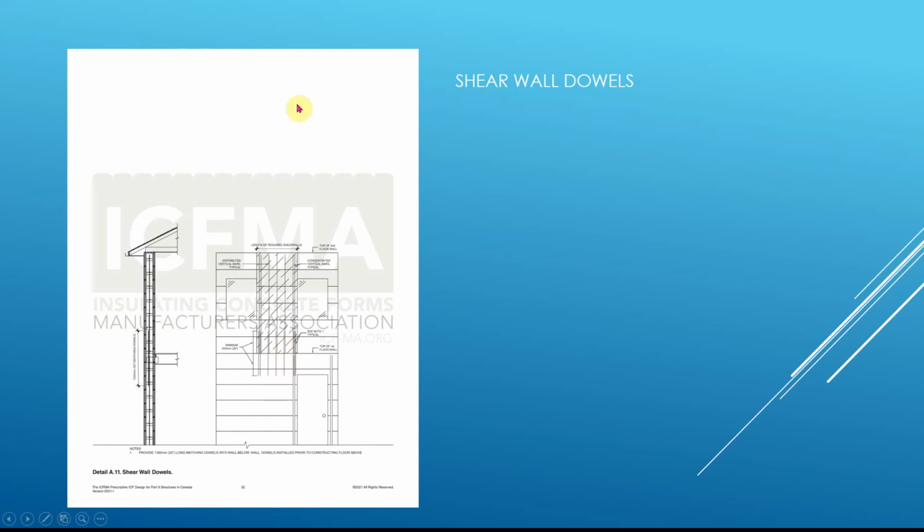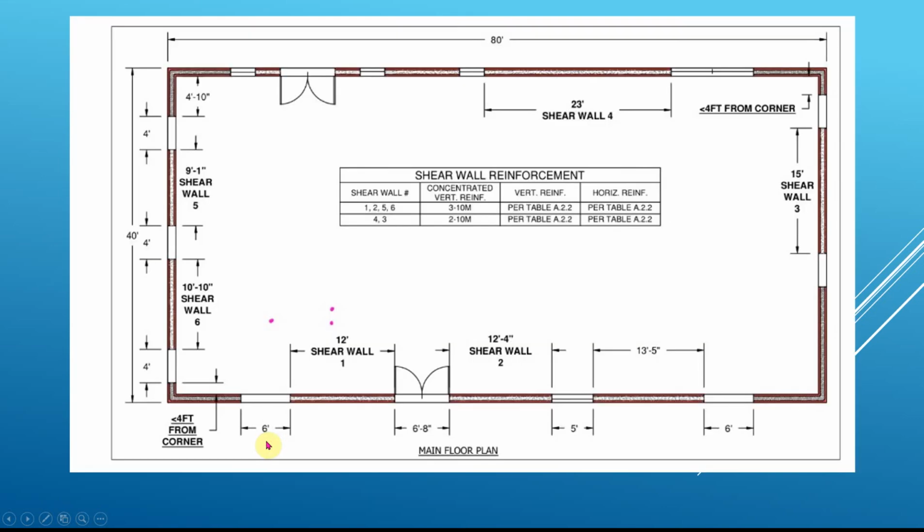So basically the shear from this wall goes all the way down to the foundation. Let's just look at this one here. This comes from the Logix corner opening bulletin. Logix and Nudura both put out a bulletin on that, but the Logix one was the one that I found explained it the best.